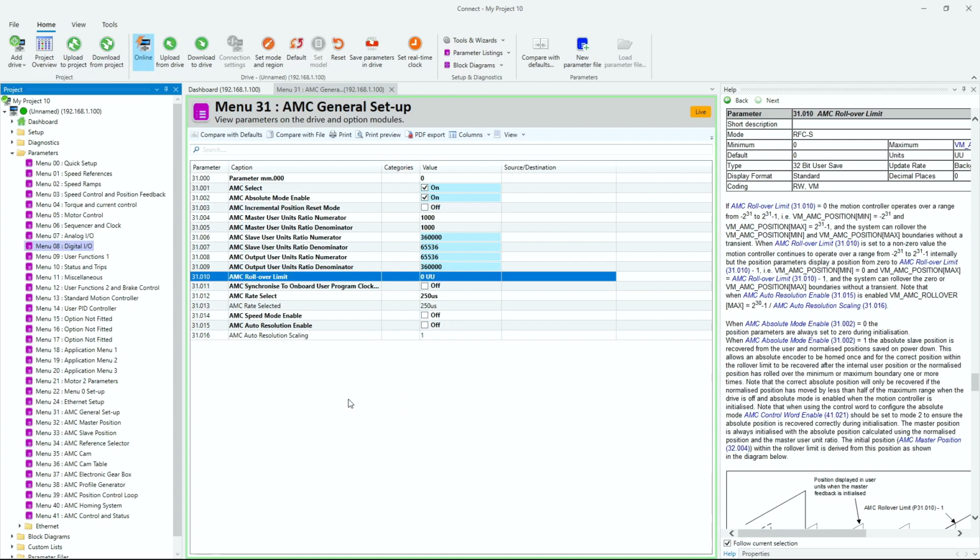And along those same lines, just general drive stuff, there are some parameters which you can't change with the safe torque off on and the run on either. The last thing you'd want to do is go in and try to change motor settings while it's enabled. It just won't take, right?